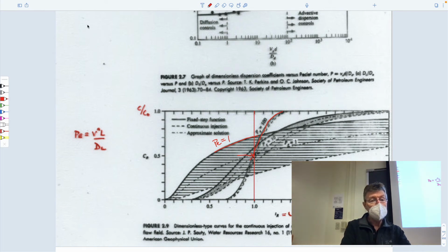It would be nice if we could use this figure to represent this behavior again for our system. The punchline is that we just need to use a dispersion coefficient which is modified to be the dispersion coefficient over retardation, and a velocity which is the velocity divided through by retardation.